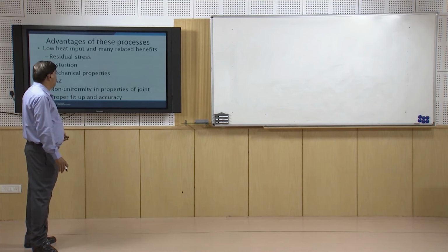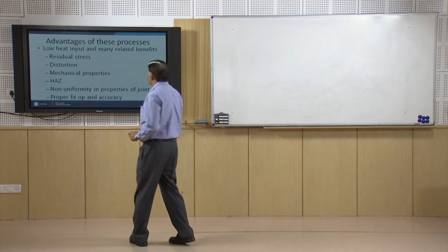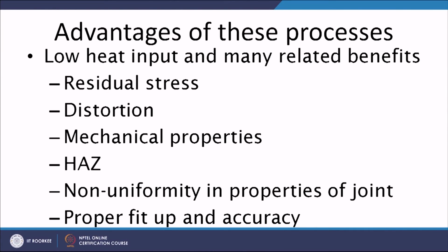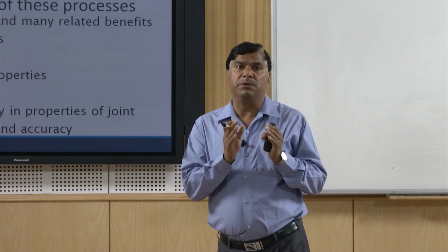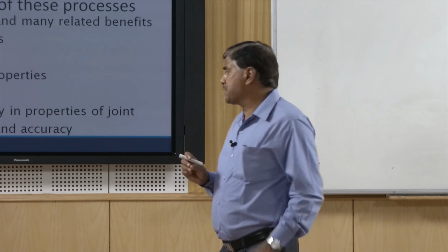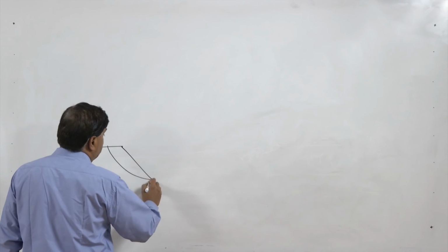of the material. So, if we now compare the solid liquid processes with the fusion weld processes, we will see that the solid liquid processes offer low heat input, because there is no fusion of the base metal, no fusion of the faying surfaces. So, since these are low heat input processes, that results in very low residual stress, because the volume of the metal which is heated and subsequently cooled during processes like soldering or brazing is very small. The extent of heating and the volume which is heated is very limited.